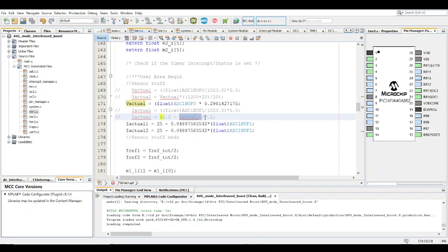The actual voltage reading read by the microcontroller in that particular pin. And it's important to know that this is the VREF for this particular microcontroller. This is actually not 5, it's 3.3, but in Proteus it's 5 for whatever reason. It's just 5. So that's why it's 5 here. Just keep in mind